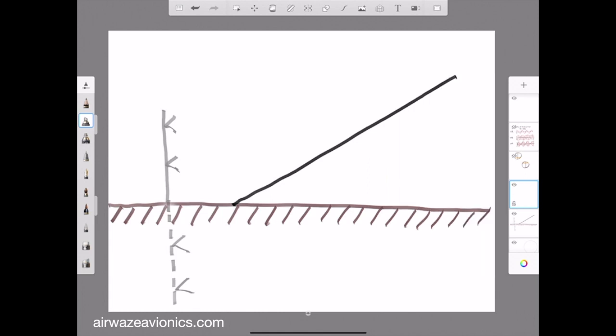The 2 antennas each radiate slightly different signals. The upper antenna radiates the UHF carrier along with modulated sidebands, and the lower radiates only the sidebands. The CW frequencies used to modulate the carrier are 90 and 150 Hz. Thus, the sideband antenna broadcasts only the upconverted 90 and 150 Hz sidebands.